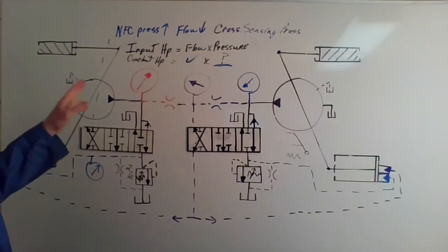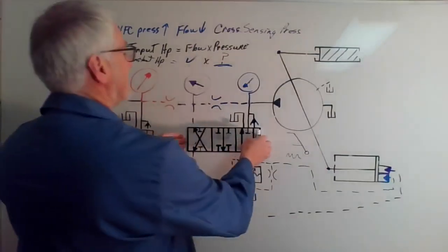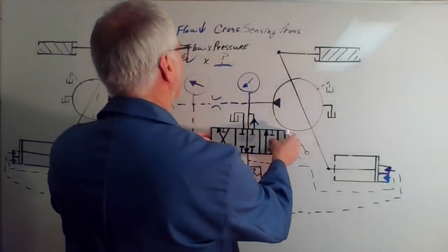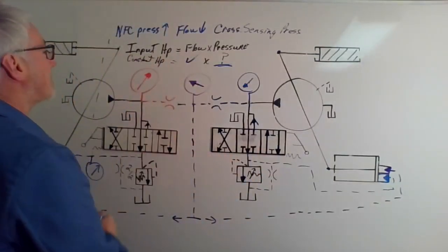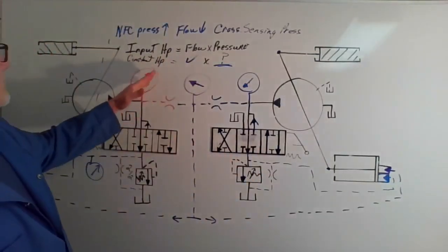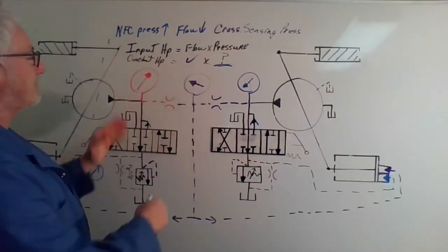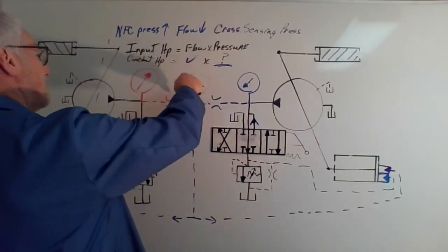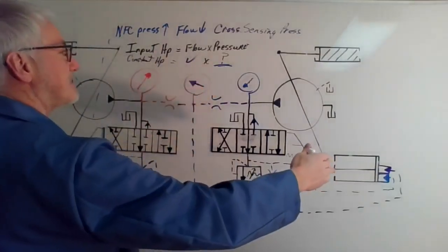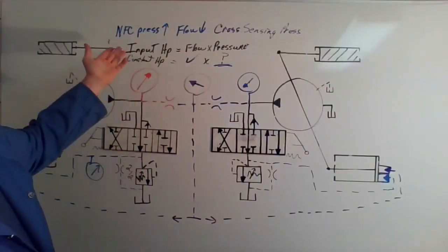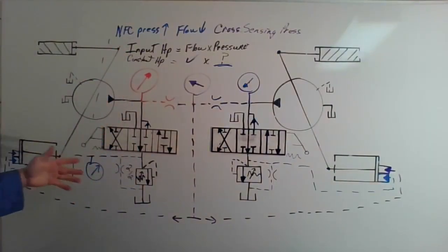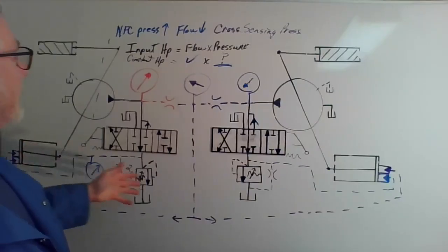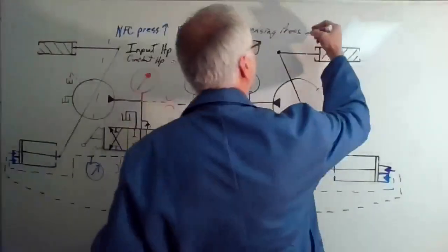Good enough. It will stay at that 10 horsepower, so 10 horsepower below whatever my engine output is, but it will always hold that constant. So if the load comes off of this one, the pressure comes off of this one, then this pressure goes down and the pump upstrokes. So the same thing happens, this negative flow control pressure, the higher that pressure, the more it wants to back out of flow. The cross-sensing pressure works exactly the same.